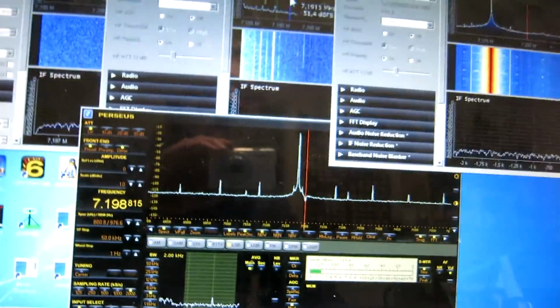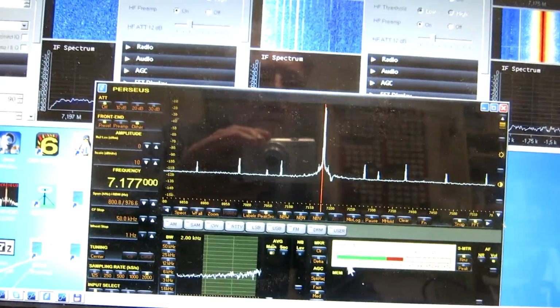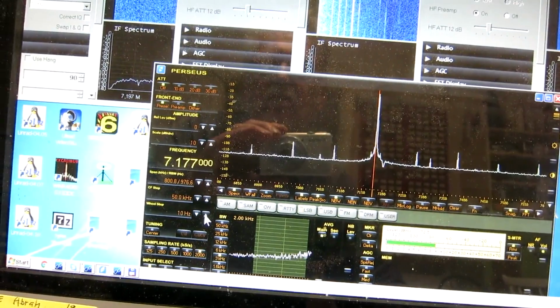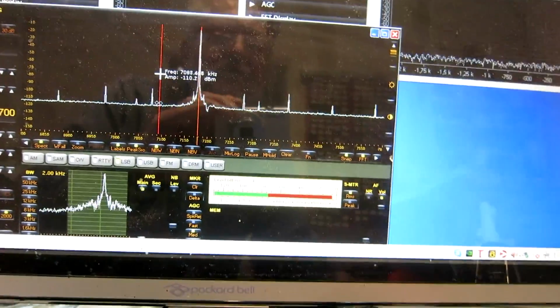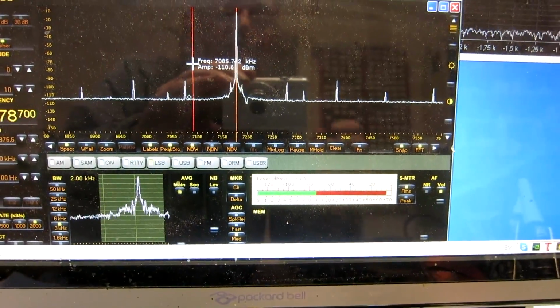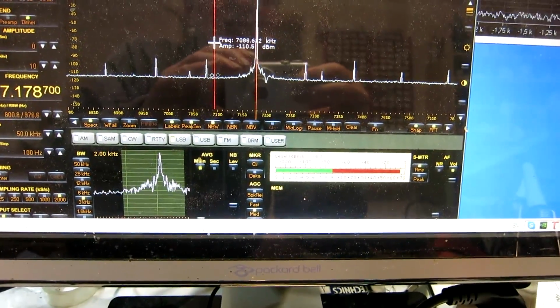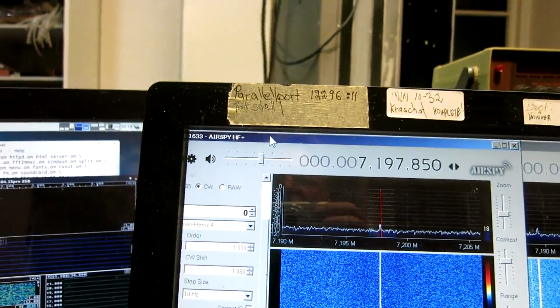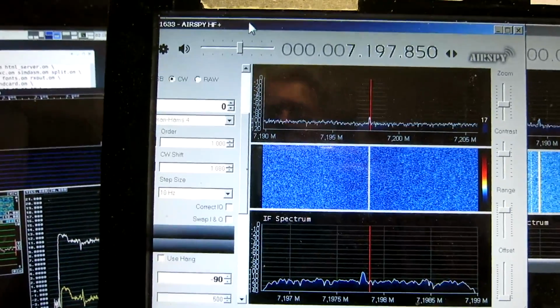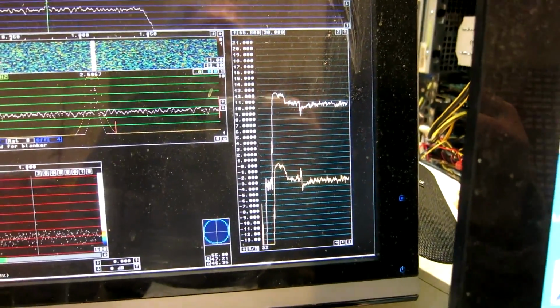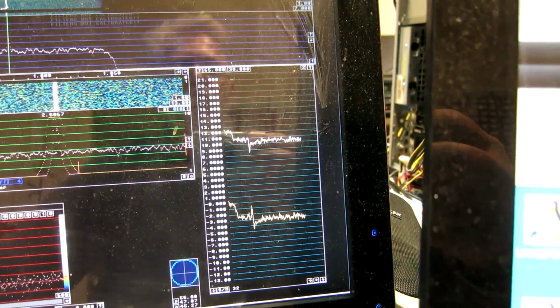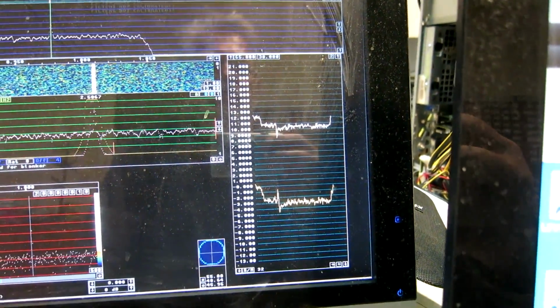And the level on the strong signal then is -4 dBm. That's the clipping level of the Perseus. I'm running now the 1633 version of the SDR Sharp with the 1.2 firmware, and I have set the level for a 3 dB loss of signal to noise ratio. I remove the strong signals, so you can see that. About 3 dB. And the signal level for that, I have to restore it, of course.